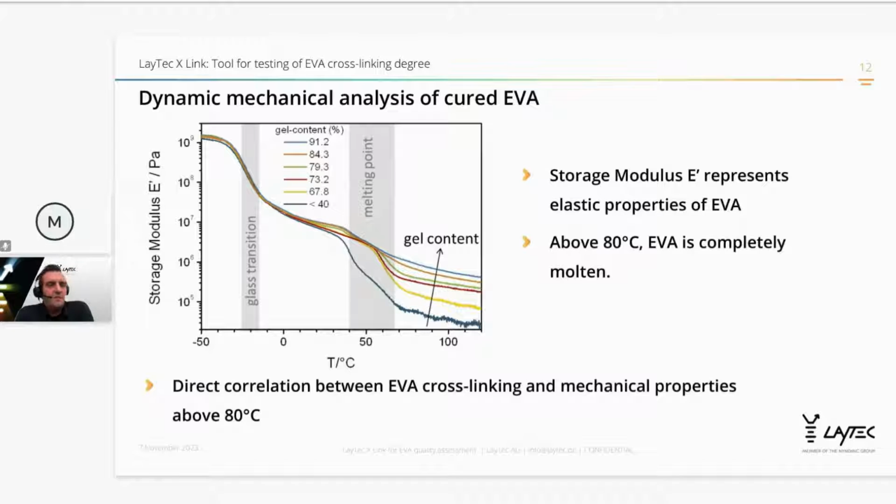So what's the mechanism behind it? The trick is that we're actually not doing just an indentation measurement, as it's usually done in polymer science or any rheological measurements, but that we're doing a thermomechanical one. This means we're heating the sample as it is measured by indentation, and above a certain melting, which is actually the melting point of the pure EVA material, and above this temperature, we do see a clear split up of the